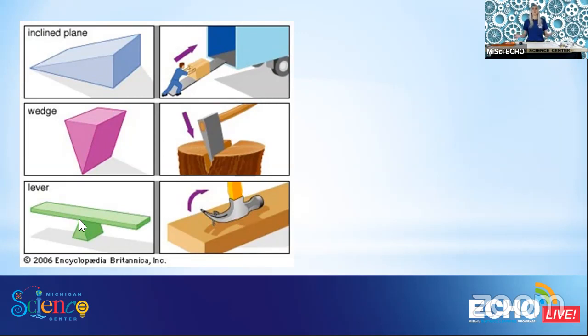But if we're using this lever in order to lift something or pry something, like in this picture of the hammer, we may need to move that fulcrum either towards or away from the point of us putting force down on that object in order to make that job easier. So we can see that we have the hammer here, and if you see the direction of the force, it's actually pulling up and over. The point of contact with the wood would act as your fulcrum, and then we're actually able to pull the nail out of that piece of wood more easily.